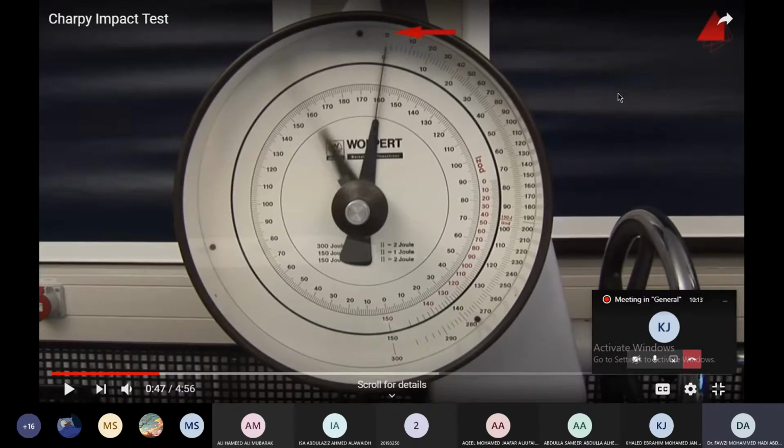So it needs to make sure that the scale shown in front of you is well calibrated, that it starts with 0, not with another number. That's number 1. Number 2, that the lubrication is good enough that it would not take part of the impact energy of the material. The lubrication is good enough not to resist the motion of the hammer.